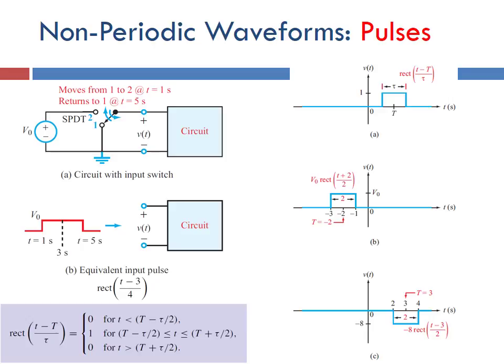And it's going to show you there your equivalent input pulse, which comes from the equations we looked at before, which is, again, the pulses are rectangular because it goes from 0, turns on for a brief period of time, and then turns off again, creating that rectangle. And so in the blue box down below, you see your piecewise function for that essentially pulse form.